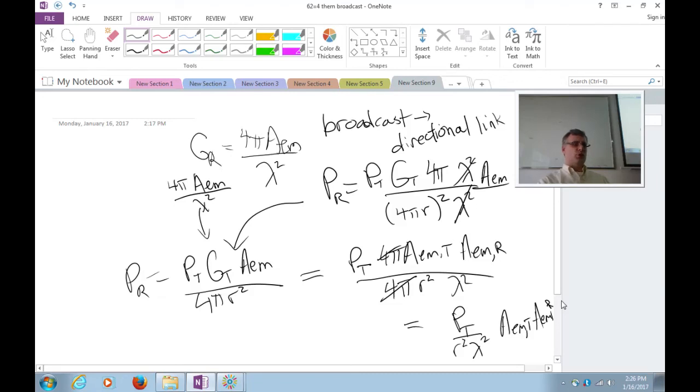So there are other issues using higher frequencies for mobile radio, but in terms of just pure path loss, if you have the freedom to point something, mobile radio is actually somewhat independent of frequency in its loss characterization. Now you go to this scenario where you have two directional antennas, you point them. What type of communications uses that commonly?